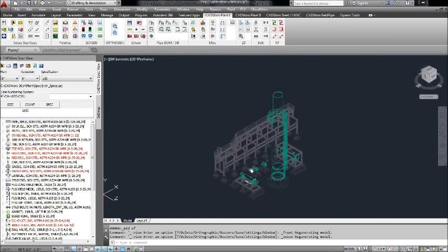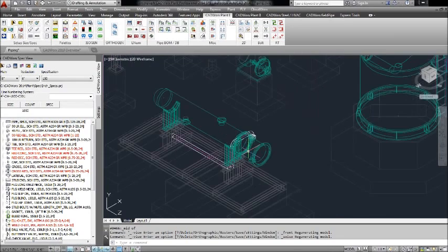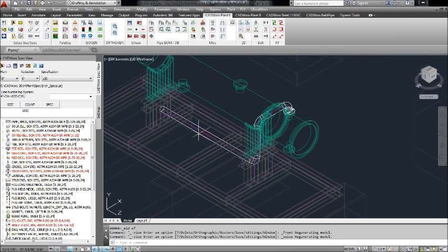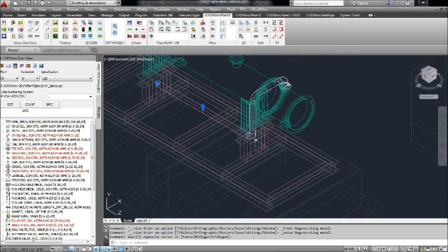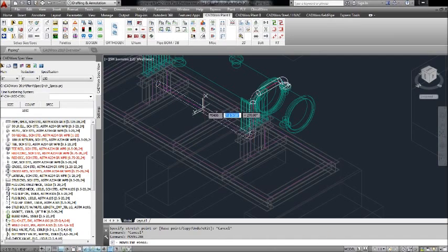Okay, I'm going to switch back to a southwest isometric view here, and I'm going to zoom in and see what we're looking at at this point. And this line right here, we want to bring this down, like I said, so that we can support it with a 12-inch stanchion on this wide flange. So I'm going to grab that square grip again, and this time it's not going to ask me for a direction to move because the elbow only turns one direction. So we can only move it in one value.